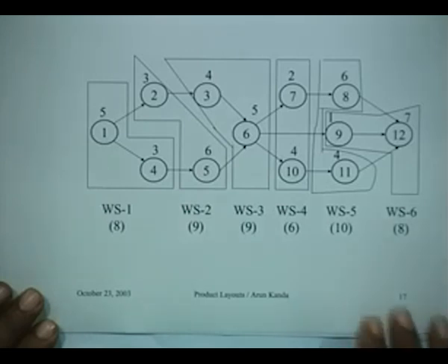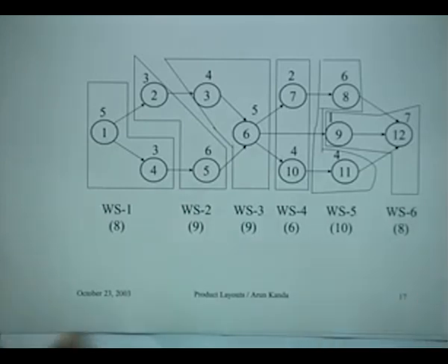However, to evaluate how good this design is, we would need some performance measures. If we want a cycle time less than 7, then instead of having a parallel assembly line, can't we have 2 machines at operation number 12, so that the effective time becomes 3.5 at that operation? Yes, that is also a possibility.